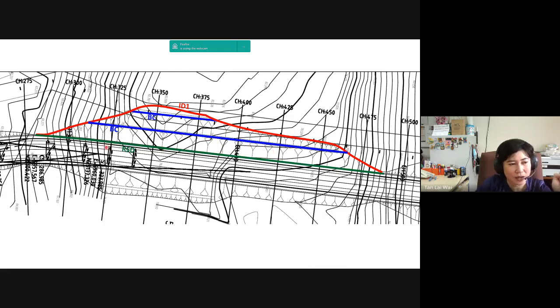How about the roadside drain? For the roadside drain, you have two areas. One from the cut slope, this part here. The other one is from the middle of the road. Of course, if you want to design the interceptor drain, you also have to account for Q coming from this bench drain and Q coming from this bench drain here. And if you have the sum here, that sum also has to consider Q from the interceptor drain and Q from the roadside drain. Okay, now let's draw this out.